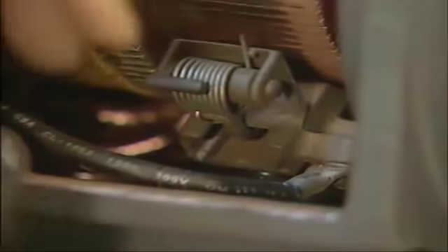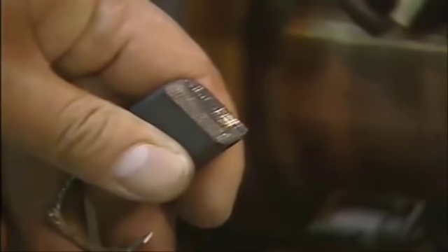A detailed check is then performed on the faulty brush and on the commutator. The brush is removed, and the brush's pigtail, the brush length, the brush's contact surface, the inside of the holder, and the bottom of the holder are all examined. In this example, the brush has worn down and it's too short. Then the commutator is inspected for dirt, contaminants, and general color. In this case, the commutator looks all right.